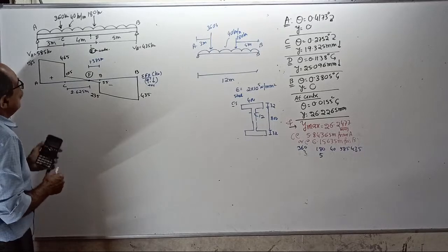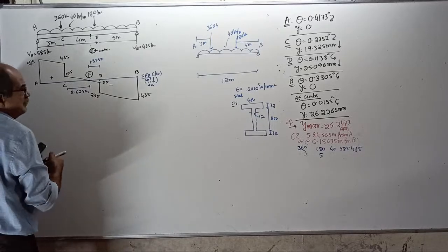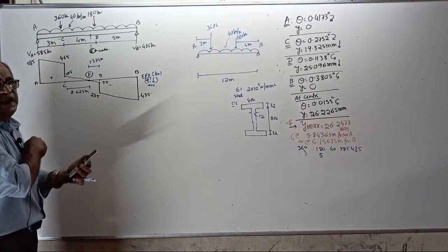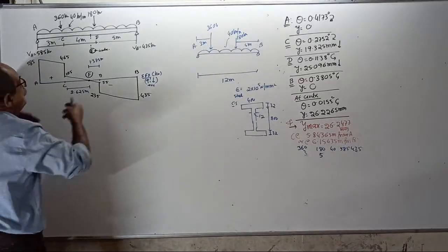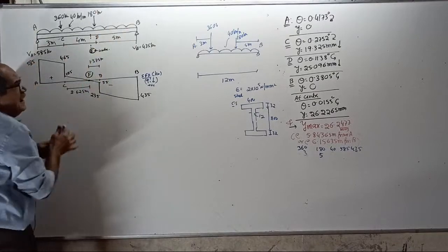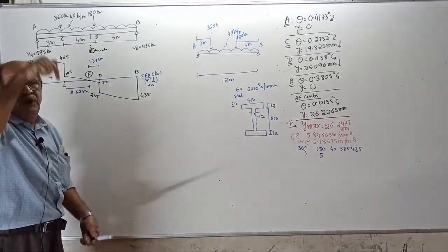Okay, that is center. Over. Now, draw the bending moment diagram. BMD is drawn on the tension side. Because why? Actually, everywhere the BM will come sagging. Sagging means tension is below the baseline.